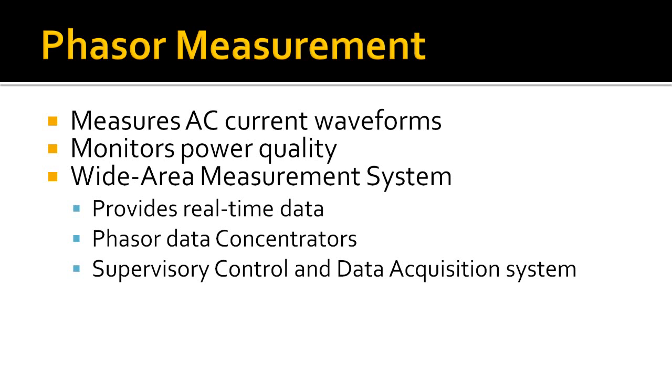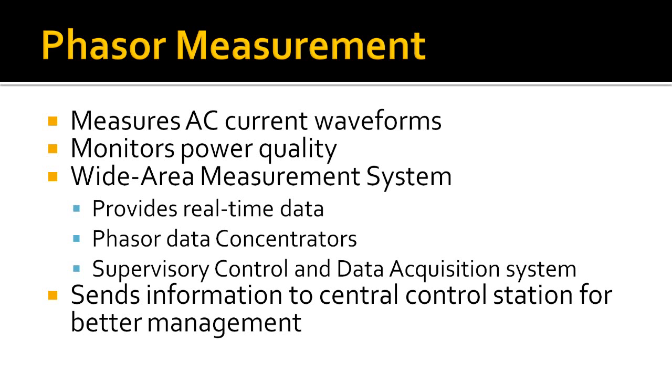Along with phasor measurement units, wide area measurement systems include phasor data concentrators to gather sample data and route it to a supervisory control and data acquisition system at a control station. Data concentrators are linked to the units through existing phone lines and manage a range of between 12 to 60 units and relay the collected information to a central facility. An entire network worth of information in relation to these waveform patterns will allow for automated systems to better manage power system distribution in real time as inefficiencies occur.